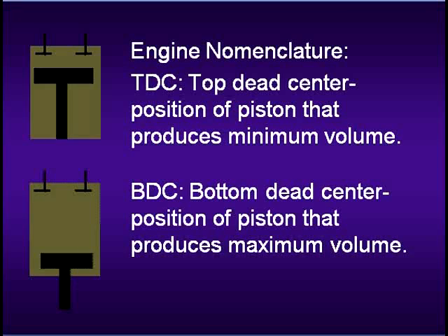Okay, a little bit on engine nomenclature that doesn't hurt to know. There's a thing called top dead center. Top dead center is when we push the piston all the way up to where it can't go any farther. Normally you have a little cavity at the top where the valves are. This is showing an intake valve and an exhaust valve that lets the air in and out. But you don't squeeze it to zero volume. If we had a 9:1 compression ratio, you'd allow 1 unit of volume for the 9 units of total volume, where the piston can't reach. Call that top dead center, when the piston's all the way up and all you have left is that little cavity of air.